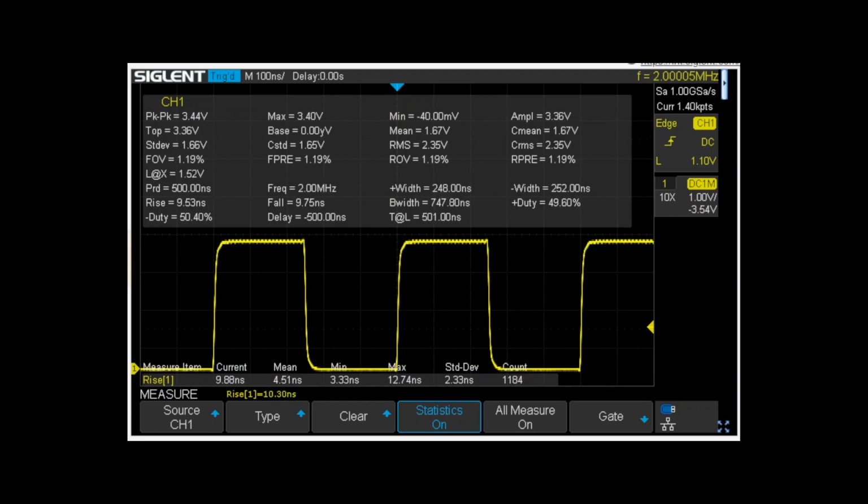So the signal looks about the same, but now the rise time is being measured at a higher value, this time around 10 nanoseconds. So that's consistent with the smaller drive strength having a slower rise time. The number is also a little bit smaller than Scopey saw. So I think the Siglent is doing a pretty good job relative to its 100 megahertz bandwidth at measuring these rise times. And both Scopey and the Siglent, both the M2K and the Siglent, are operating according to their theory. They measured rise times consistent with their bandwidths.